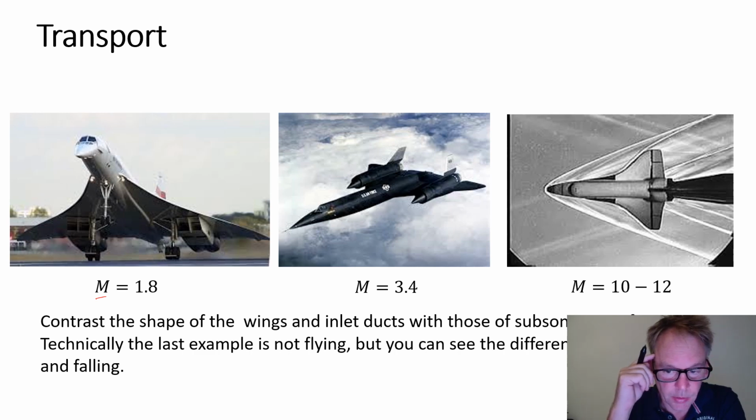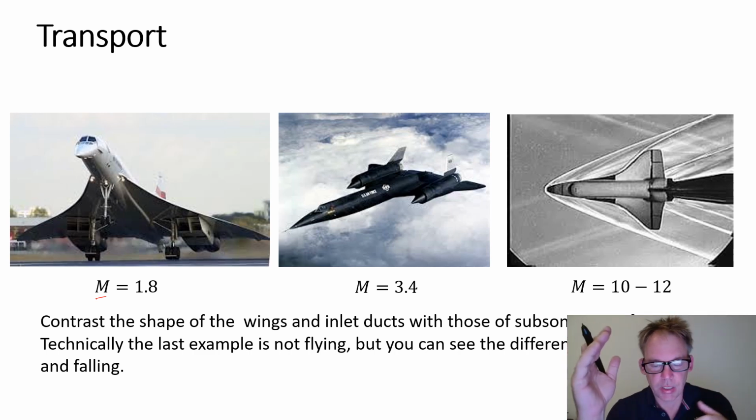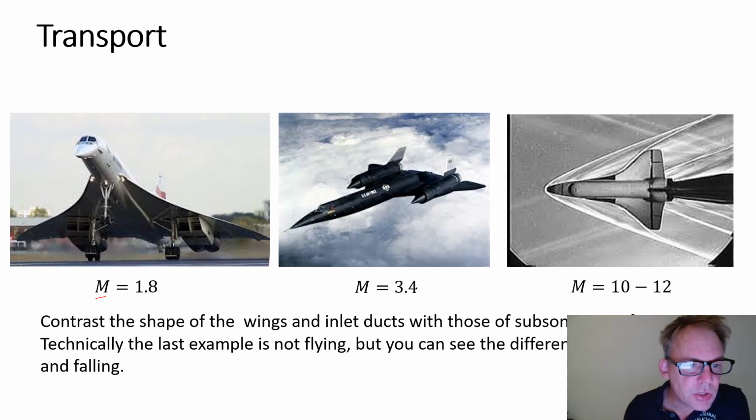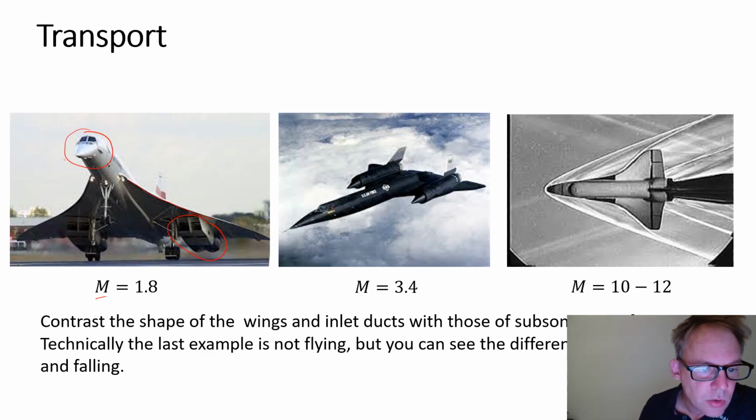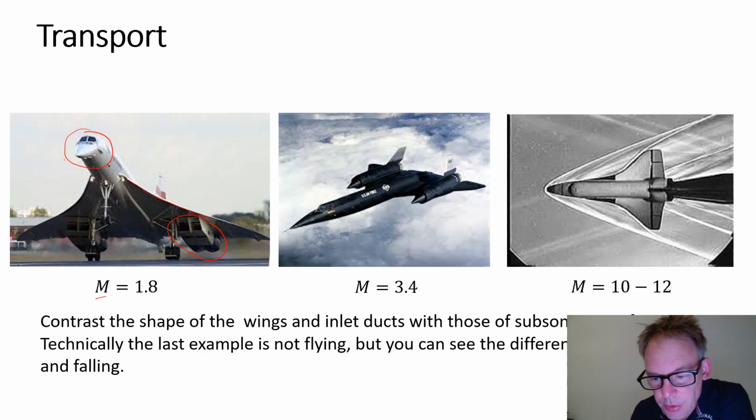The wind models are actually in the Science Museum, very small. We'll talk about dynamical similarity later. But the interesting thing is it's got a delta wing, a flared delta wing, an adjustable cone, so we'll see a big feature of supersonic craft is variable geometry, and we've got gas turbine engines with a variable inlet geometry to ensure that the inlet flow is shock-free.